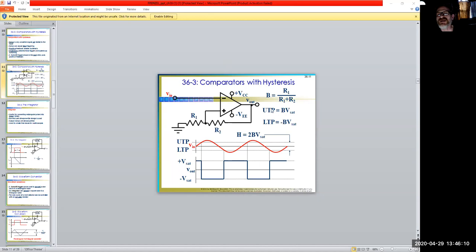So we look at this circuit. We have a voltage divider model tied in on the non-inverting loop in this case. If you remember the previous ones, we typically tied in on the negative terminal for a feedback loop, and that was the negative feedback control. But now we're going into the non-inverting side, providing a feedback loop and leaving the inverting side wide open. If you see an op-amp wired up this way, that's the type it would be.